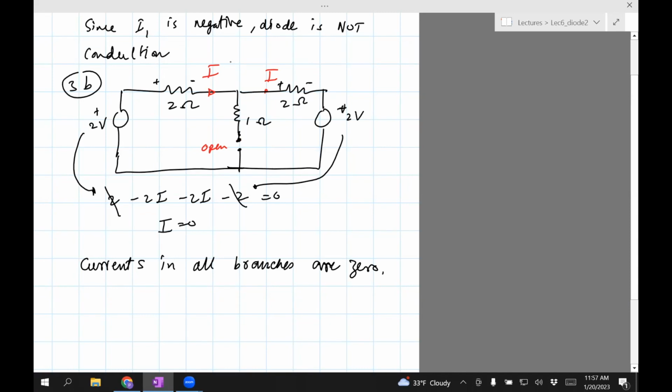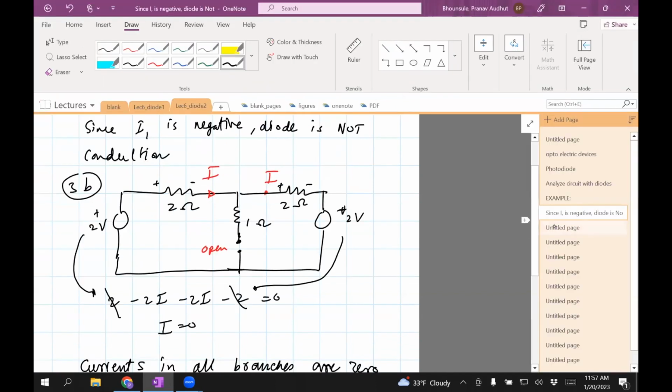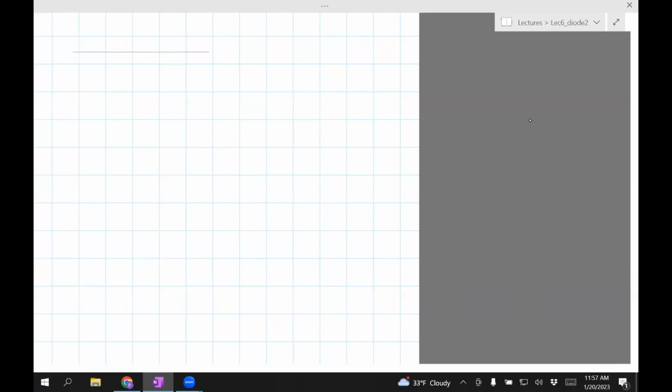Okay, so this is how you would solve a circuit involving diodes. I will give you 2 problems for you to solve later on. You might want to read on the internet for information and then try to see the reason how this works. So it's something called a flyback diode. A flyback diode is used in a circuit to protect a switch from sparking. The way it's connected is as follows.